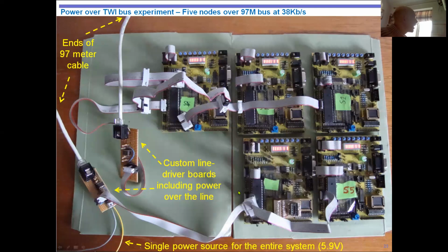This is the system I use, just to show you what I did here. I also did, you've heard of power over Ethernet, I expect. Well, I invented my own power over TWI. So I had a single Ethernet cable with the power line and the TWI going over this. This was 97 meters long. These two are on the one end with the power supply, and these three were a long way away. And there's a drum of cable in between here connecting these together. And actually, these were tested down. They were physically about 30 meters away, but the cable is much longer. It was on a roll for test purposes.